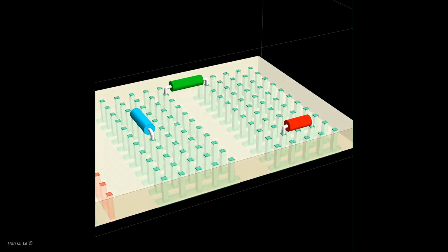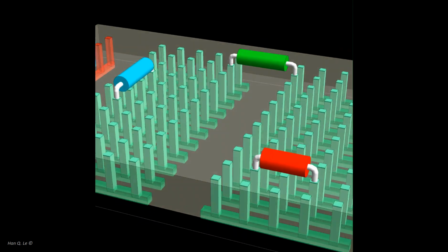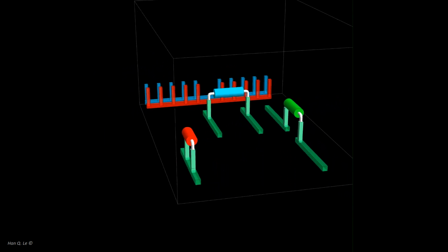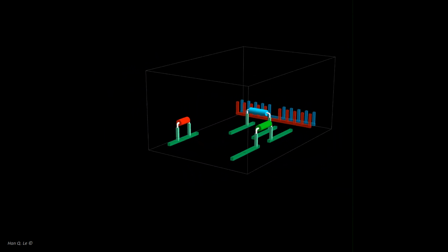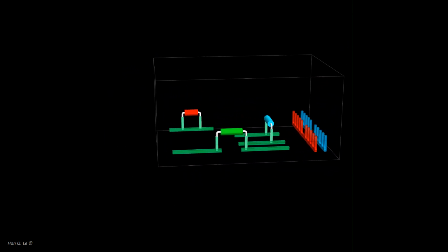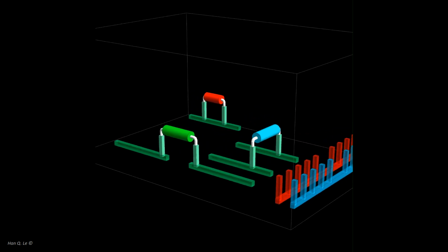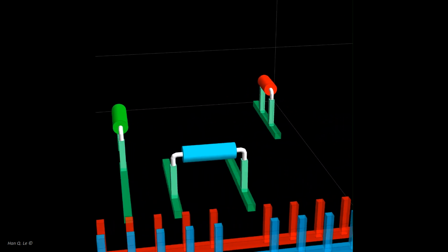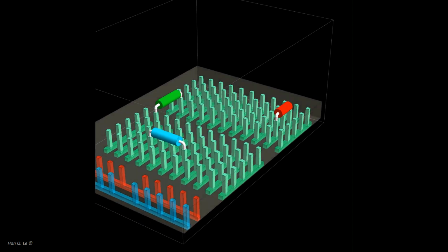The two terminals of the red resistor are connected, or shorted together. It means the current will prefer to flow through the conductor underneath, not the resistor. Hence it cannot be used. The blue and green resistors are in a correct configuration for usage.